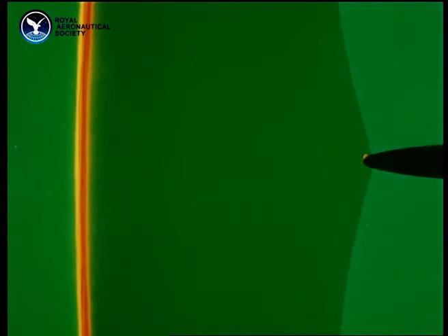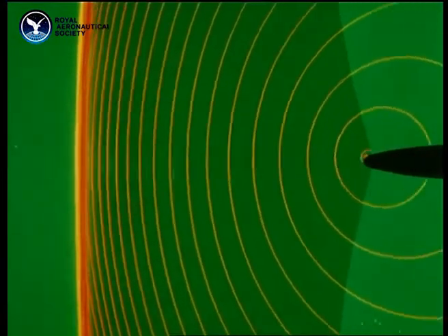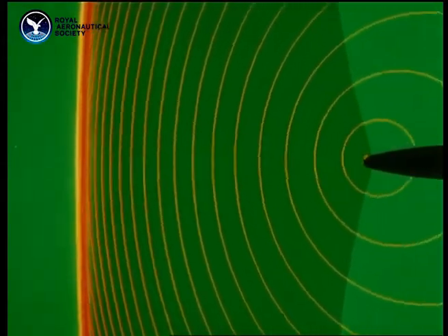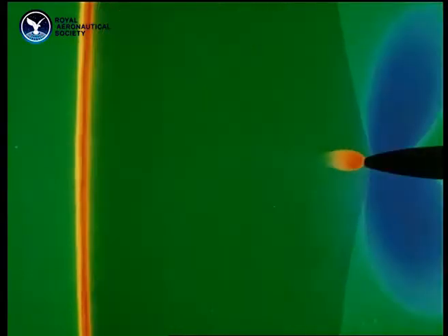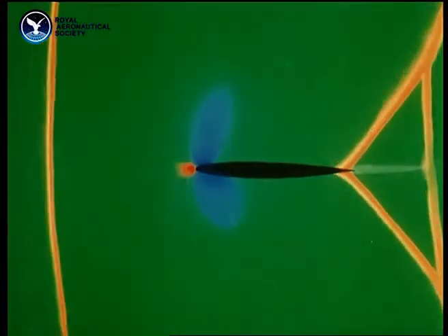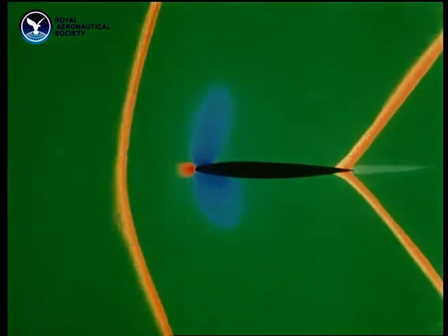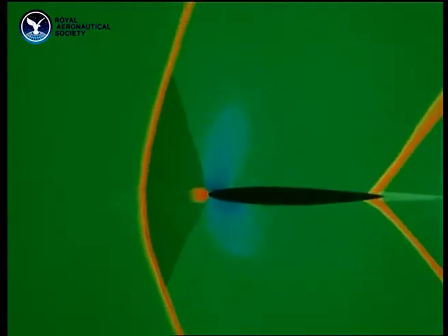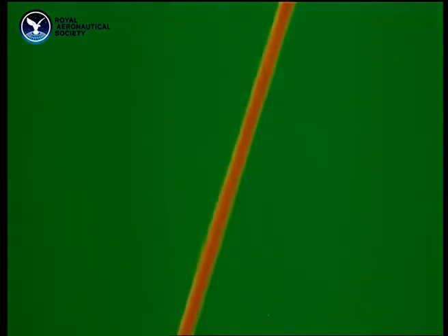Like the shock waves on the wing, the bow wave is formed by the constant piling up of pressure waves, this time from points near the leading edge inside the subsonic region. As speed increases, the bow wave comes in quickly towards the leading edge, but there's still a subsonic region in between. A shock wave oblique to the airflow usually has supersonic flow on both sides of it. A normal shock, one perpendicular to the airflow, always has subsonic flow behind it.